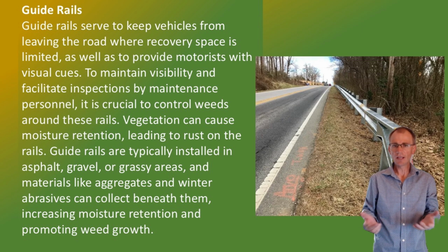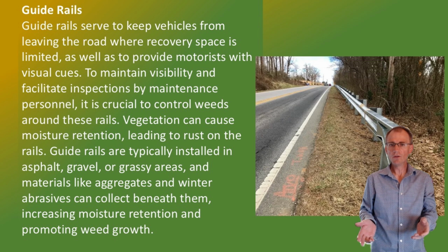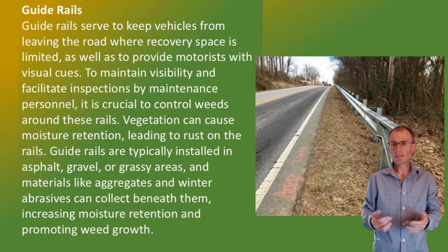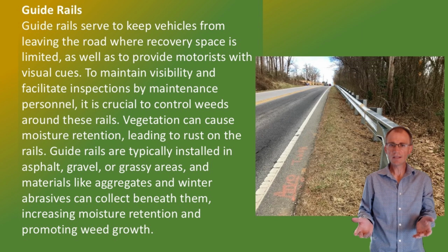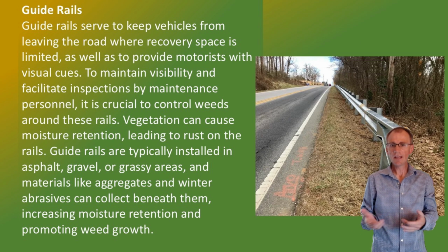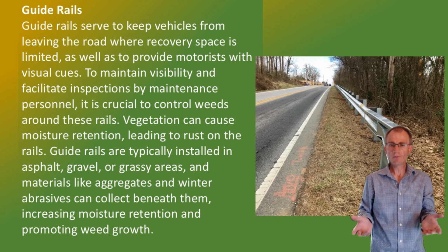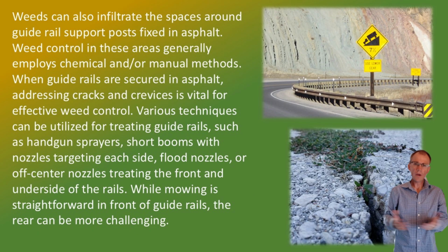Guide rails are typically installed in asphalt, gravel, or grassy areas, and materials like aggregates and winter abrasives can collect beneath them, increasing moisture retention and promoting weed growth. Weeds can also infiltrate the spaces around guide rail support posts fixed in asphalt. Weed control in these areas generally employs chemical and/or manual methods. When guide rails are secured in asphalt, addressing cracks and crevices is vital for effective weed control.